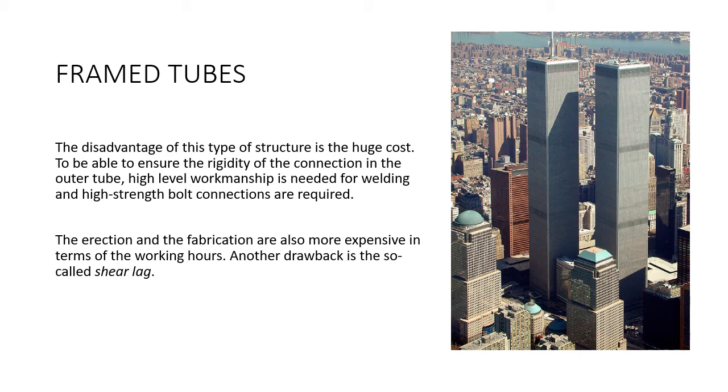To be able to ensure the rigidity of the connection in the outer tube, a high level of workmanship is needed for welding, and high strength bolt connectors are required. The erection and the fabrication are also more expensive in terms of working hours. Another drawback is the so-called shear lag.